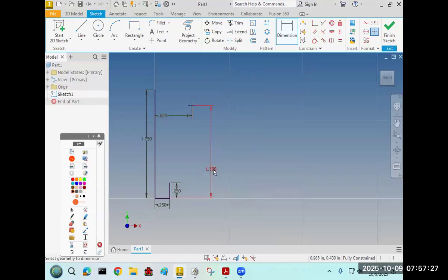Okay, and it looks kind of wonky with all these dimension lines all over the place, but it's kind of like that. So we just have this work point that is in the right place, and once we have that, we can just get a line tool that goes from there to there. Boom. And it's already fully constrained because that point is fully constrained.